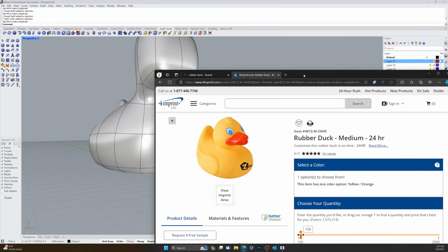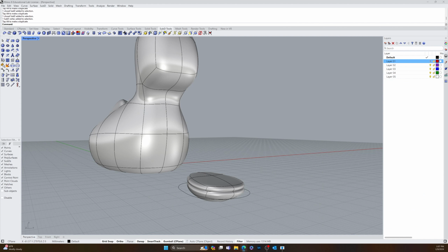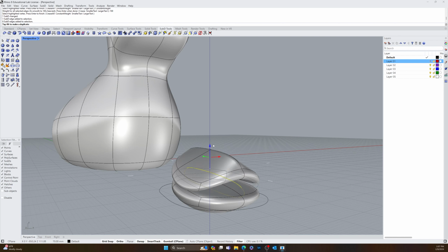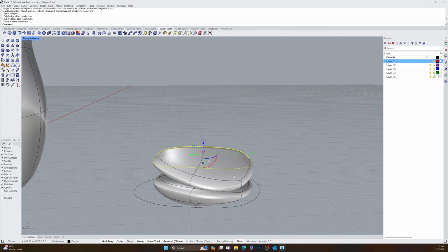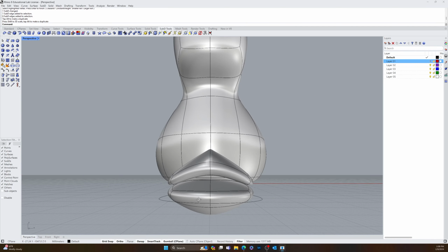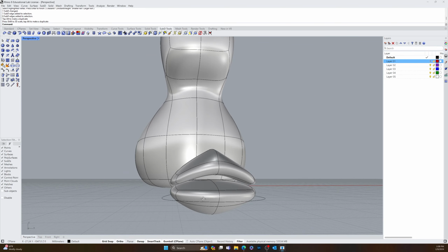So this is what we're looking at. So I'm going to go ahead and select these two lines here, and I'm going to go sub D crease. And I'm going to go from constant weight here. I'm going to just do 100 for a nice heavy crease. And pull it up, up, up. And then I'm going to kind of scale those two. No, can't scale those in the way I want. Yeah, it's starting to look a little bit better though.